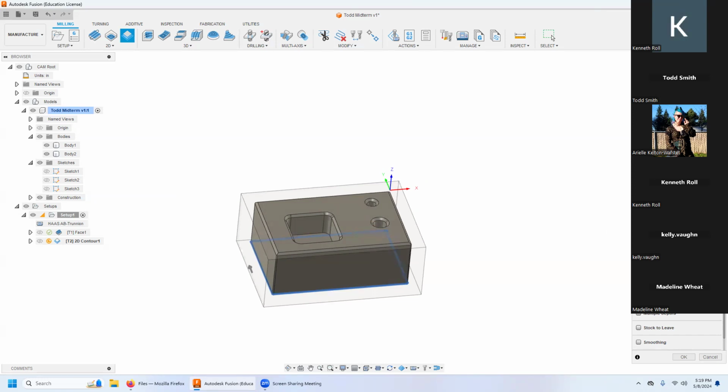My finish feed rate is going to be much slower than that. We're going to take that value and divide that by 3, and it's going to be pretty close to 40 thou. It's not going to do the math for us this time. That's okay. Thus, we have a calculator over there, so I'm just going to put in a 40 thou.